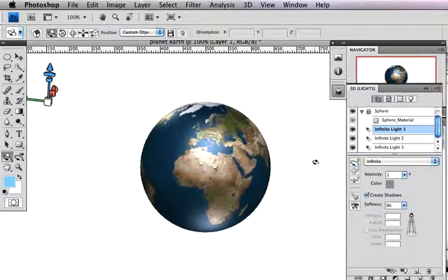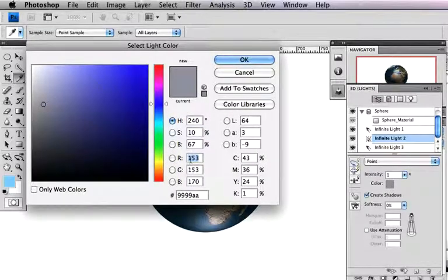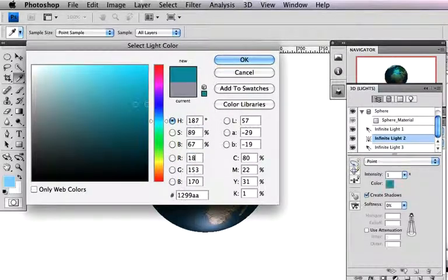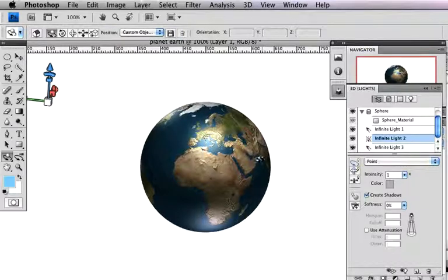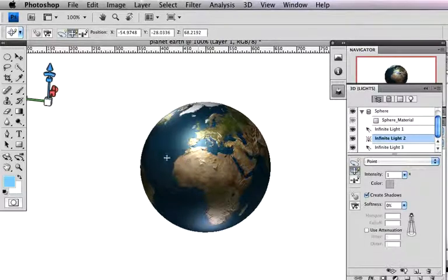and click on OK. Then we're going to come down to our light 2, and we're going to set this to point, and again we're going to set its color. We're going to set it to 180 for all of them. Let's click on OK. And then we can slide the lights that we're generating around by clicking on our light source over here, and we click on this little pan movement here, and we can just start to move those lights to start to add a little bit of focus to where we want that light to hit. So I'm just going to bring that up just a bit.